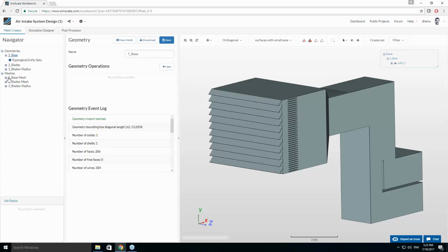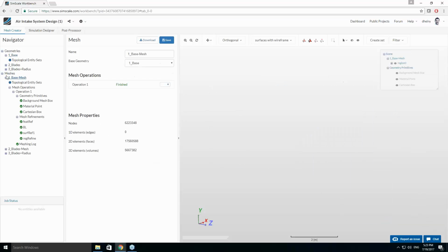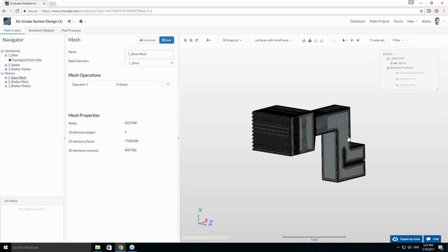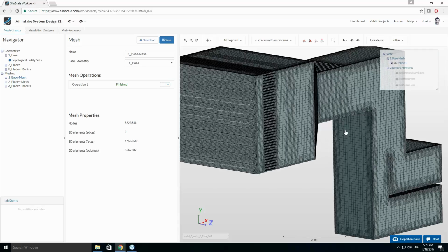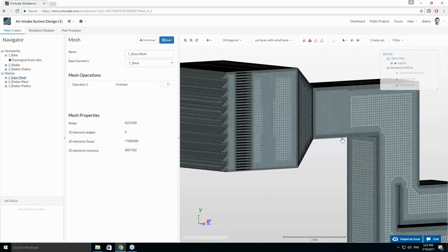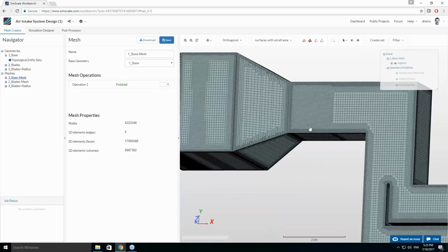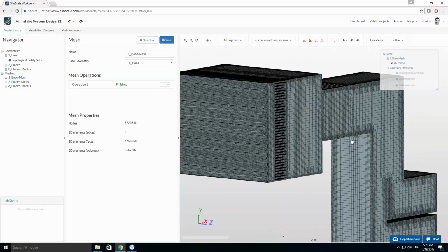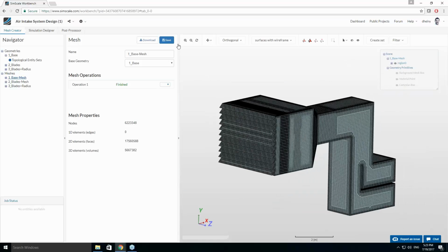And so as a first step, what you do on SimScale is you create a computational mesh. So you basically discretize your CAD model into small pieces, into small cells, and that allows you then to use simulation methods to predict the physics in it, right? So here you can see lots of very fine cells. SimScale provides both automatic as well as parametric meshing technologies that you can use to create a computational grid.